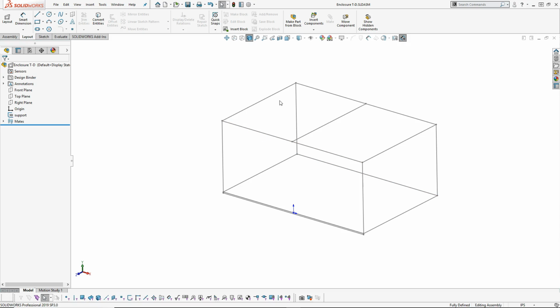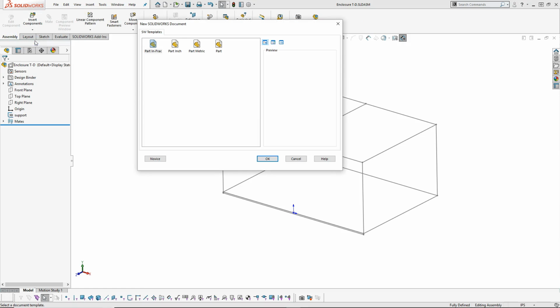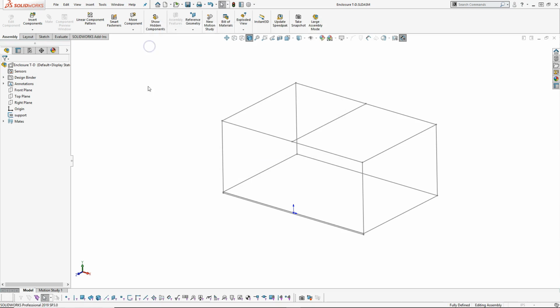I'm not planning on putting my geometry directly on this sketch from the assembly. I have to reproduce it in the derived, in the new part. Alright, so we're going to go in, create the part. I don't like picking the plane, so I click out and it's going to follow the same origin as the assembly. If I pick a plane other than the front, I believe, then that's when it starts skewing the origin. That always freaks me out, so I usually just end up clicking somewhere and saying it's in that orientation. I don't have to worry about it twisting on me.